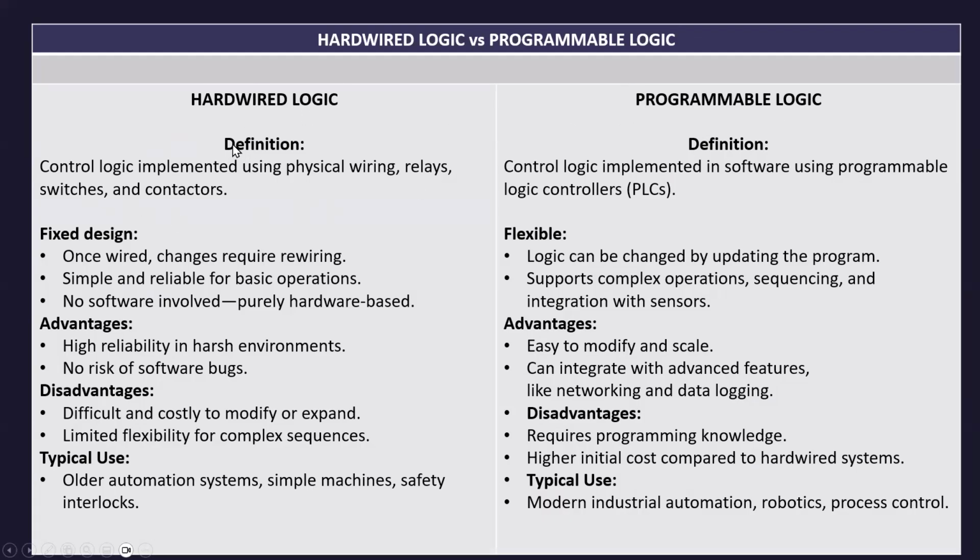Hardwired logic: control logic implemented using physical wiring, relays, switches, and contactors. It's a fixed design. Once wired, changes require rewiring. Simple and reliable for basic operations. Well, you can't have a virus in it because there is no software. No software involved. Purely hardwire based.